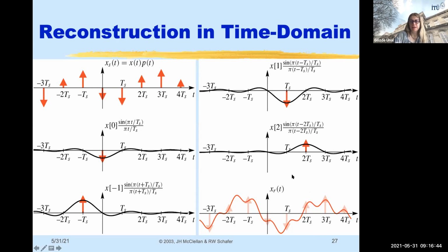And we've seen how easy it is to see or prove in the Fourier domain. It was a sinc filter in time domain, but in frequency domain, it's an ideal low pass filter, rectangular form. Just multiply the spectrum to get rid of all these replicas, and we get the original signal.